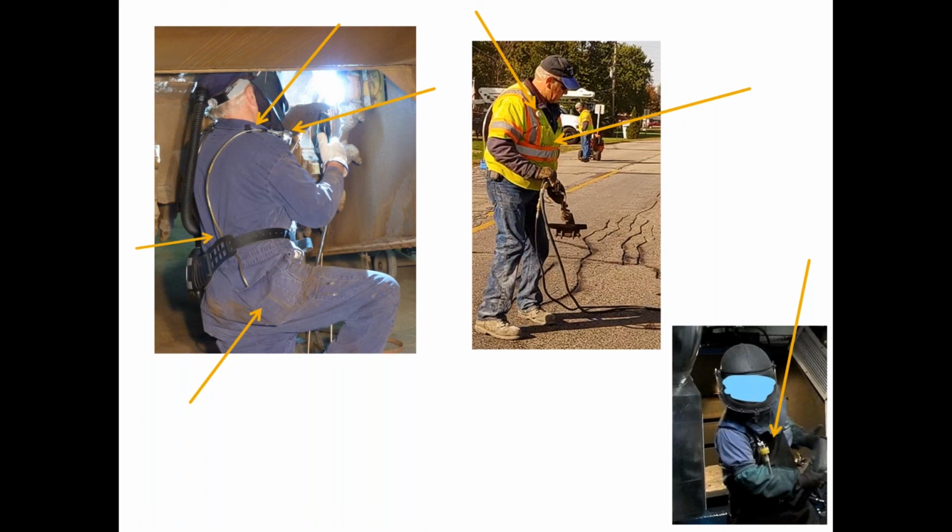There's a 2-point clip up near the end, and you can see that the sampling device is placed outside his PAPR helmet. In the second picture, I put this one in there mainly to emphasize this was an outdoor job. This was a cold morning in Wisconsin, and he started out with heavier clothing on, so I had to reposition the sampling device during the day to account for that. And lastly, the bottom picture is just another example of a cyclone outside of an air supplied hood.